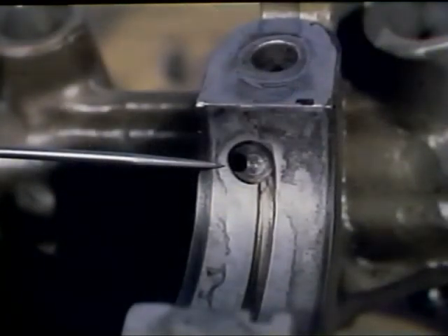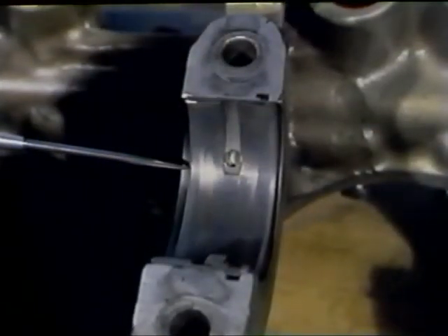In the crankcase, a pump is used to force oil through drilled passageways to lubricate crankshaft bearings through bearing supports. These bearings use soft metal inserts mounted in a steel shell that fits into the bearing supports to hold the crankshaft centered.